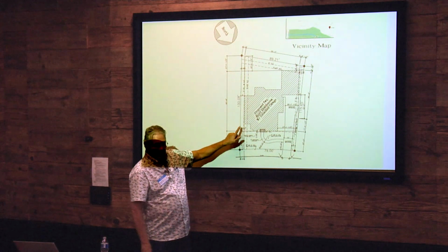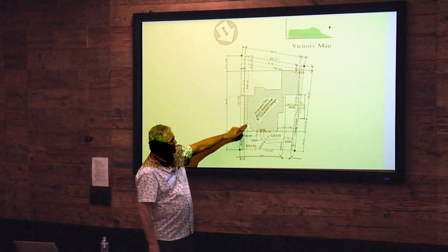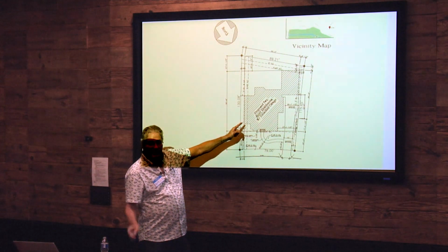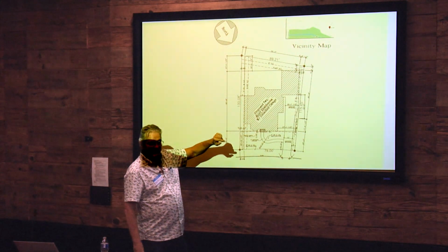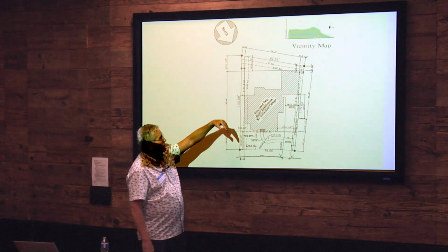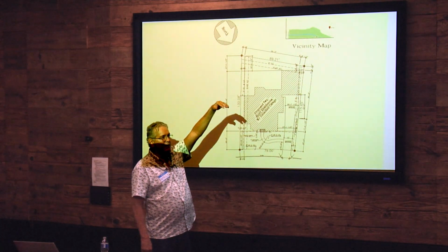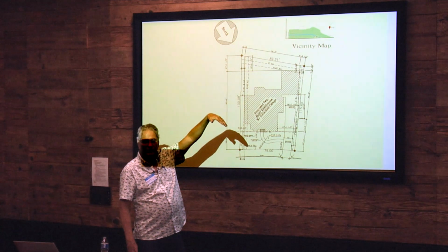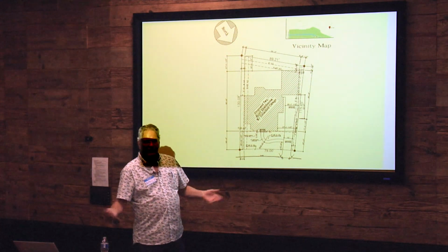The 5 is the width. So it's an easement that goes 5 feet this direction, and that doesn't necessarily mean it encroaches or ruins how the house sits, but the 20 refers to where the easement starts. So 20 feet up is what that means. So an aerial easement means 5 feet out from the property line, 20 feet up. If a part of your house is in that space that's 20 feet up, you're encroaching on the easement. Anything 20 feet and down, you're fine.